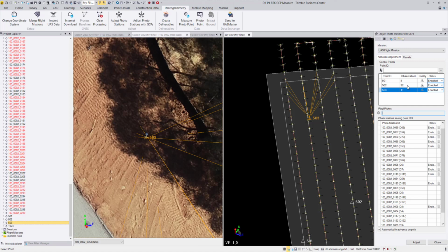So therefore, please always be aware, signalized control points help drastically to measure. I could also measure in the control point 502 a couple more measurements just by guessing where is the center of the squared panel. And this is really helping in many cases, in contrast to a natural control point, where it's sometimes difficult really to find it and to measure it.